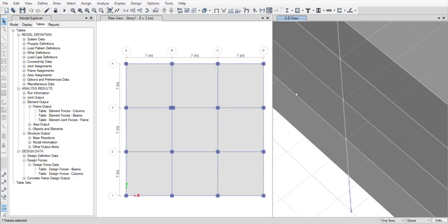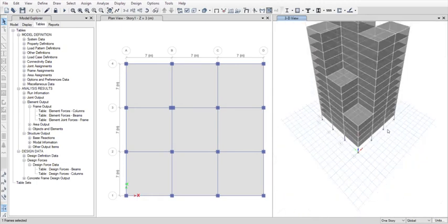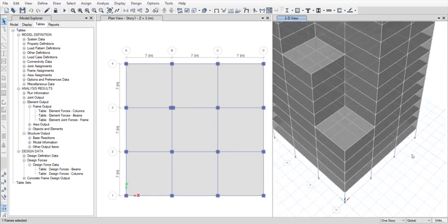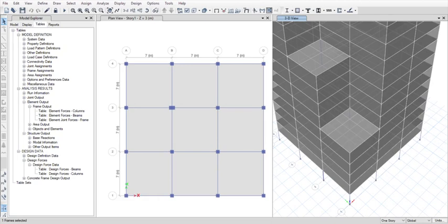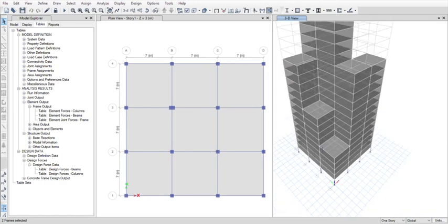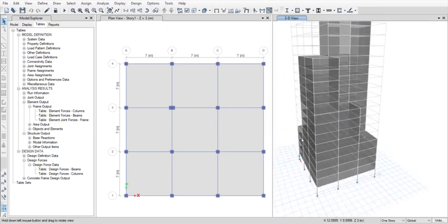After noting it down, I told you there are two types of column, right? But to get the dimensions of the column, it's very simple. Now go to select properties and frame sections. Most of the column sections are 550 cross 550. Let me go to 600 cross 600, select and close. Now when you observe closely, select the rotate option. Now just rotate it.